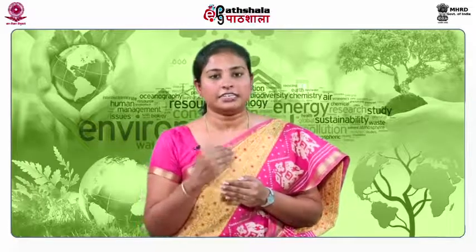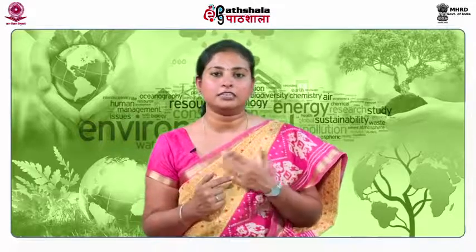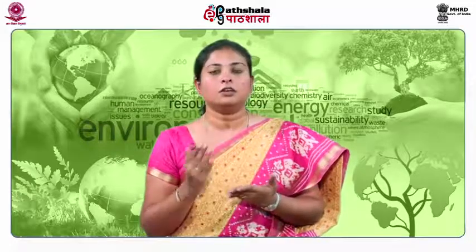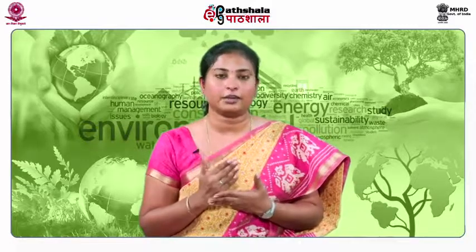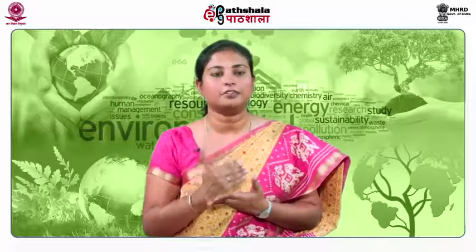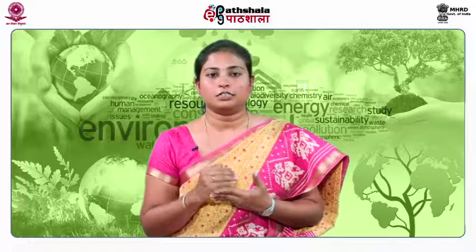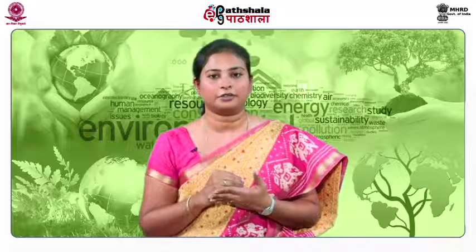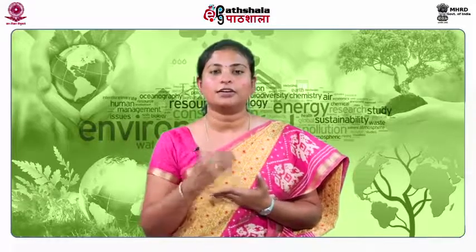The leachate generated from the anaerobic LFBR is collected and recirculated to maintain the moisture level within the system. As I told you earlier, 35 to 40% of moisture is generally required to accelerate or speed up the degradation of waste. The leachate generated during the process is not sufficient to maintain the moisture within the LFBR in an anaerobic landfill bioreactor. In that case, you can use either sewage sludge or non-hazardous liquids or any storm water for maintaining the moisture within the bioreactor.